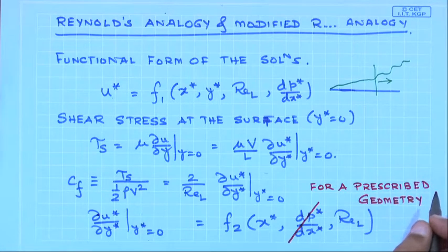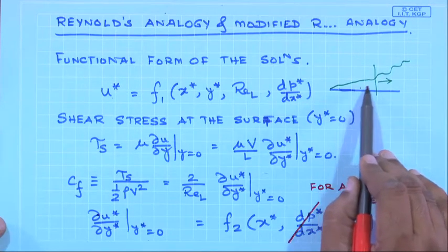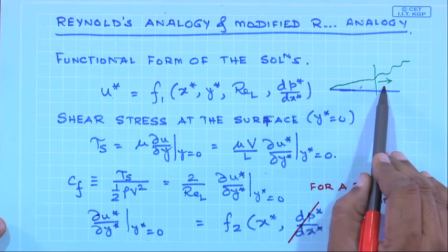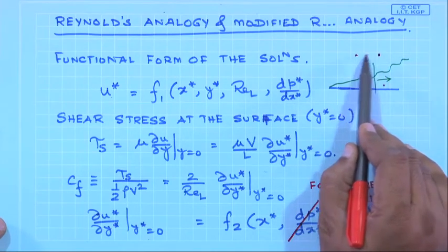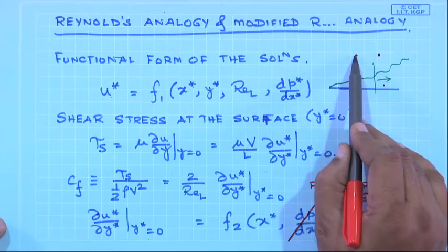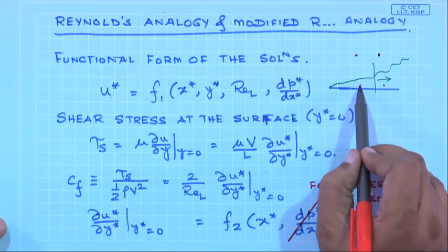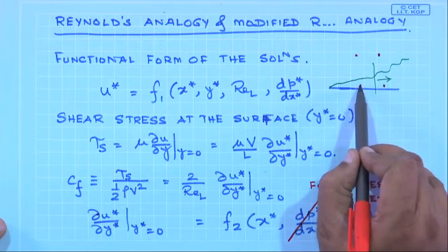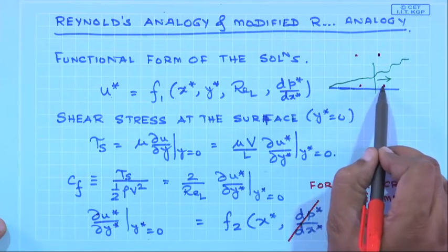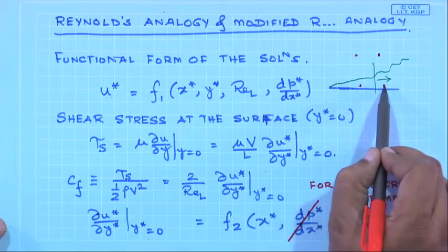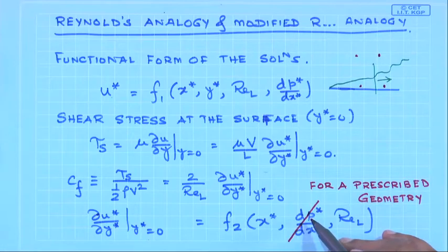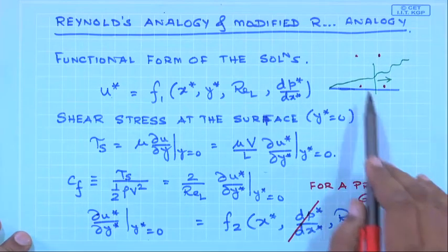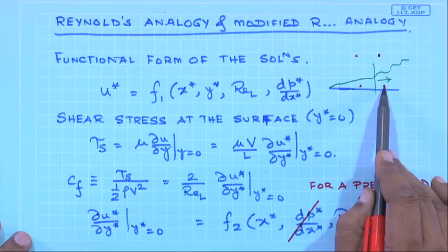Remember that what I have told you before is inside the boundary layer the flow is viscous, outside of the boundary layer the flow is inviscid. So, there is no effect of viscosity in here. Since you have the effect of viscosity present inside the boundary layer, you cannot use known equations which are available to provide the pressure drop as a function of distance.